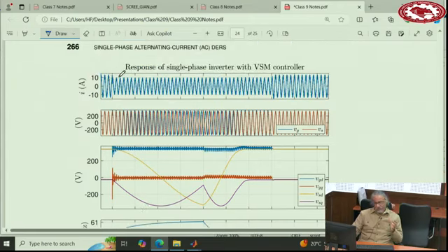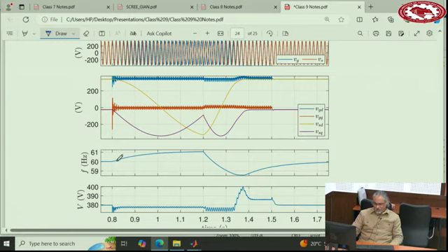There is a load there, so now the converter will power the load. The current will go down a little bit to make sure that it provides the required voltage for the load. The voltage remains almost the same magnitude, however, it starts changing the angle because the grid is no longer there, so it starts shifting. If you look at its frequency, it will keep going up until about 61 hertz because the load is small. So it uses a droop like a synchronous machine. If the load is small, the frequency goes up.